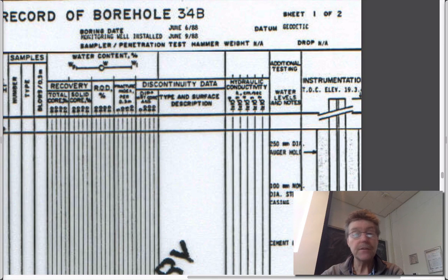If you're doing a test to measure permeability, all you do is you pour water into this domestic white plumbing tube, 1-inch diameter white tube. It raises the water level to some height, and you just record how long it takes to drop down with time. And that slope of the rate of drop says something about how quickly it's flowing into the material around it. You can convert that directly into hydraulic conductivity and permeability, and you plot that here.